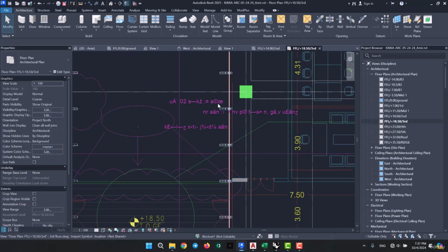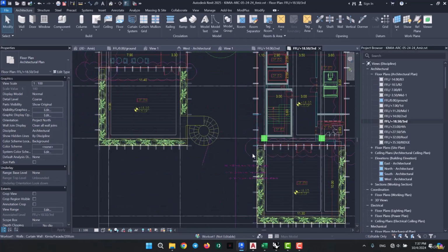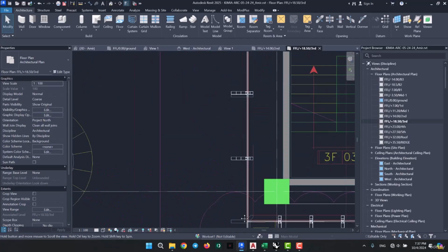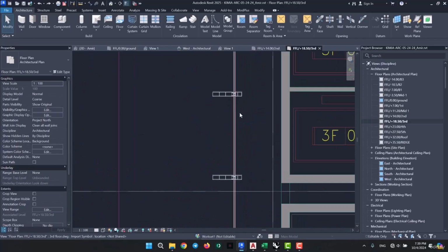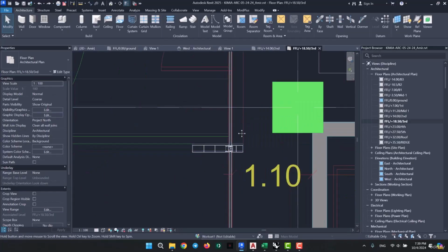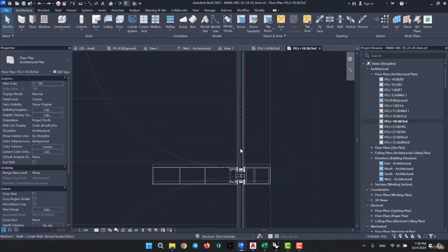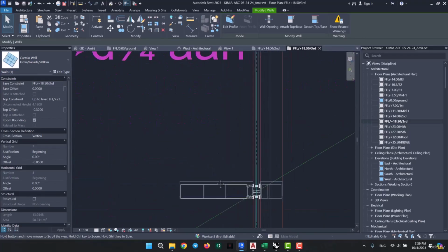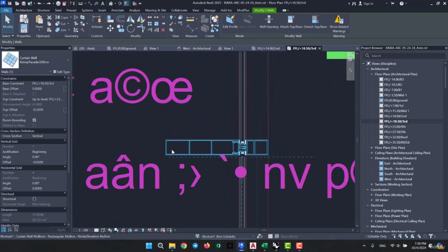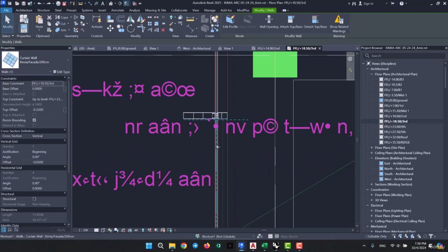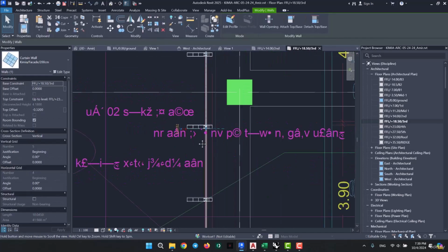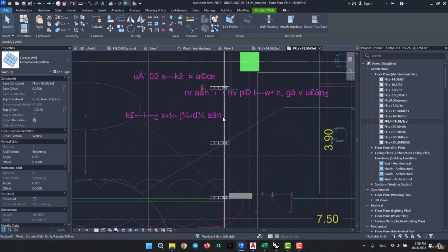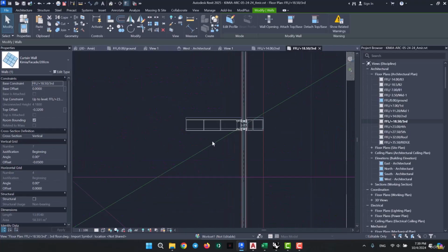I'm going to check the entire line to see exactly where the problem lies. As for these first mullions, we've already adjusted them earlier. And now let's go further up and see what's going on. Here we can see that there is a fixed distance between each mullion. We're going to check the whole thing to make sure it goes for all of them. And also remember that these mullions are for a different curtain wall because we've drawn one curtain wall per each set of mullions which are at fixed distances.